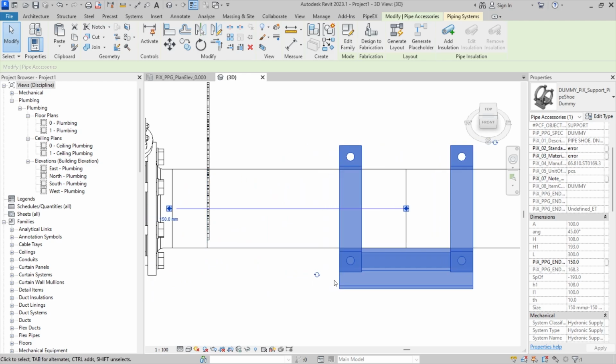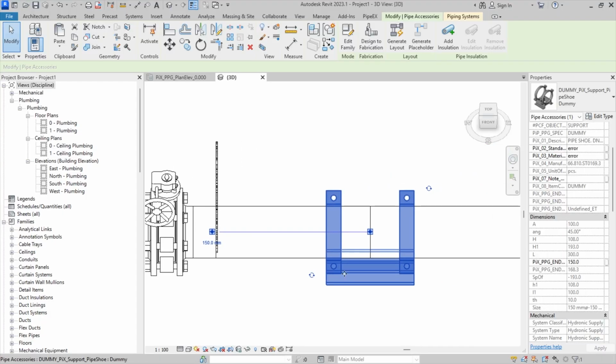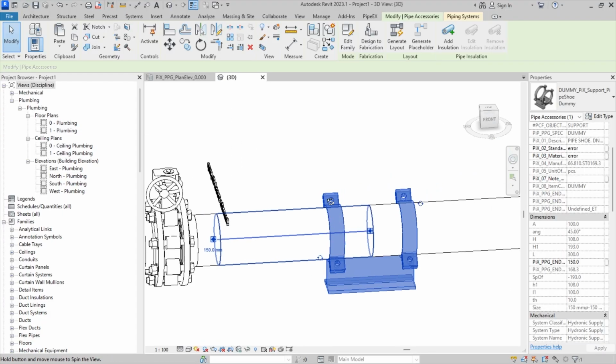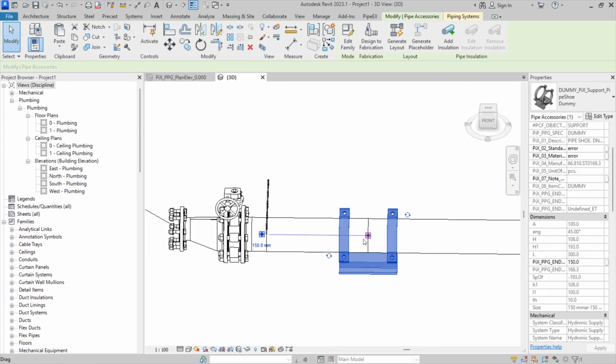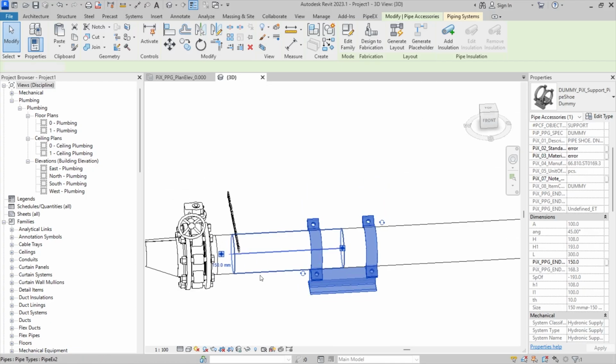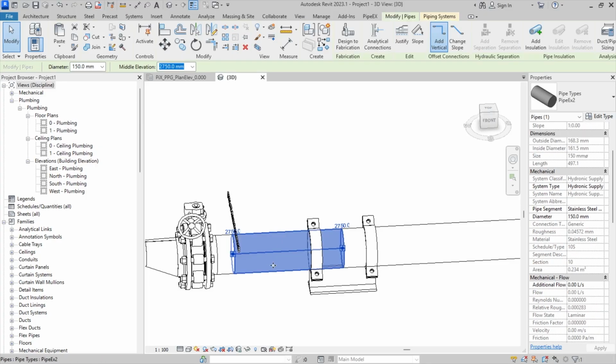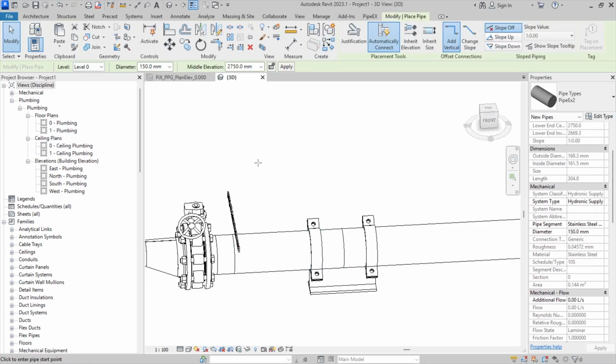The simplest one will be, of course, to add the drain from the side view, but let's cover two cases right now. So we're going to create two drains. Actually, we're going to create one drain and one instrument connection. So the drain we will create from this view, and for that what I will do, I will click on pipe, then create similar, and on create similar I will select, for example, let's say DN25 I would like to have,